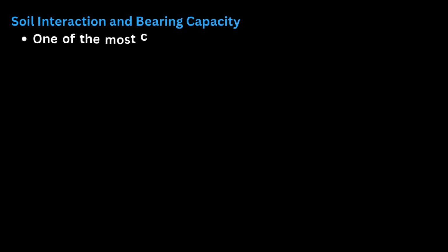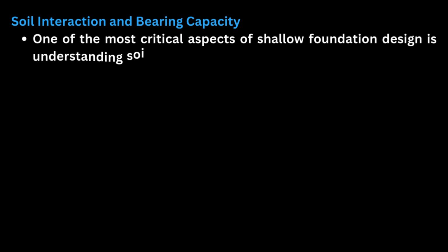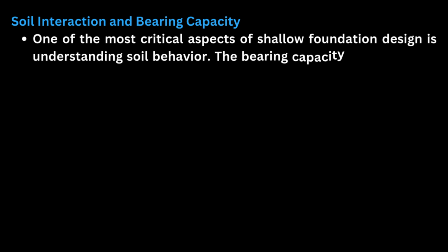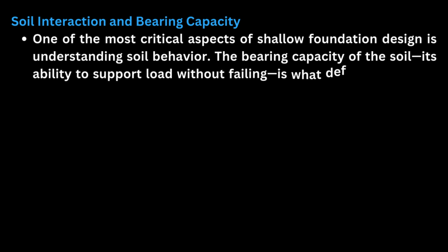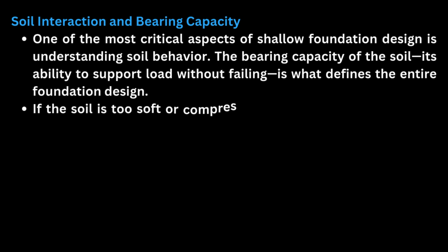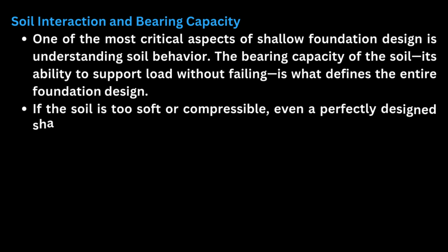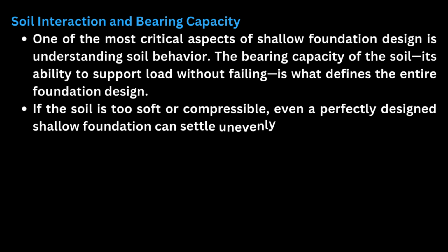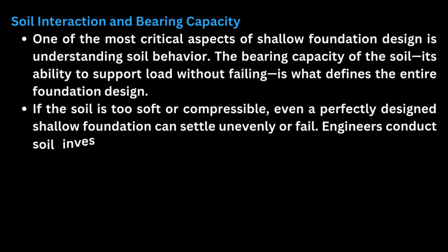Soil interaction and bearing capacity. One of the most critical aspects of shallow foundation design is understanding soil behavior. The bearing capacity of the soil, its ability to support load without failing, is what defines the entire foundation design. If the soil is too soft or compressible, even a perfectly designed shallow foundation can settle unevenly or fail.